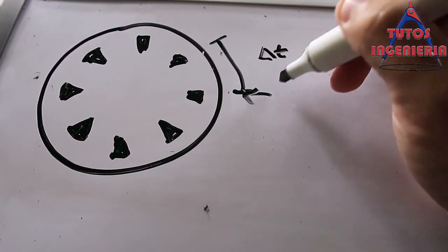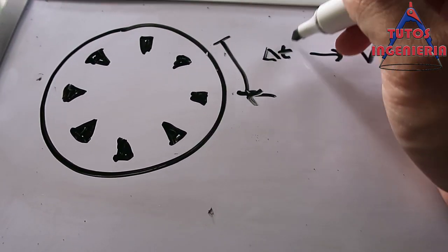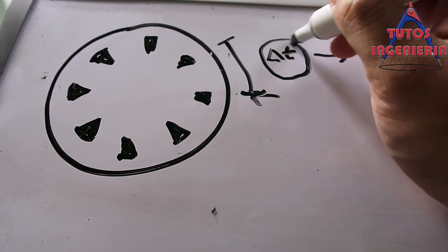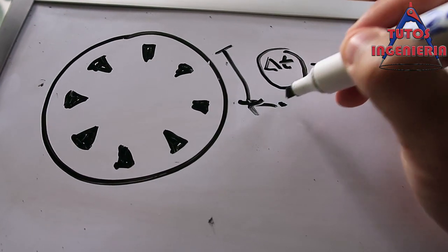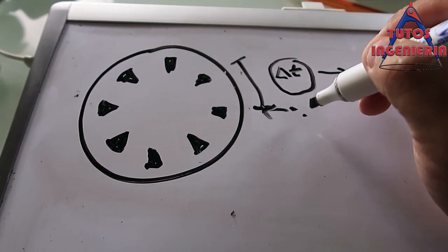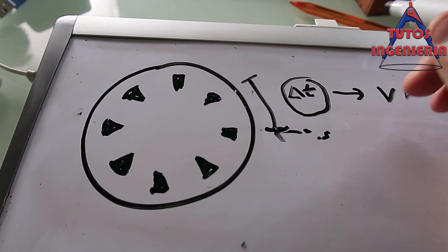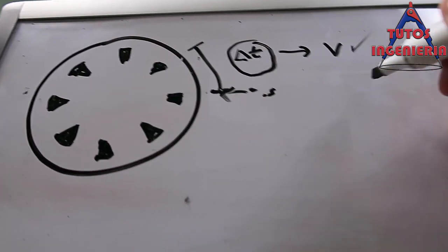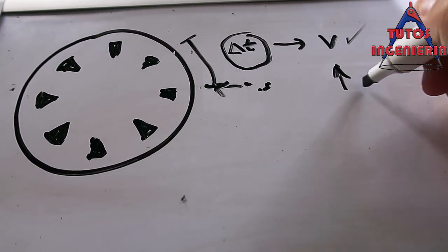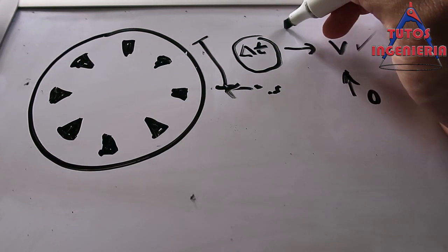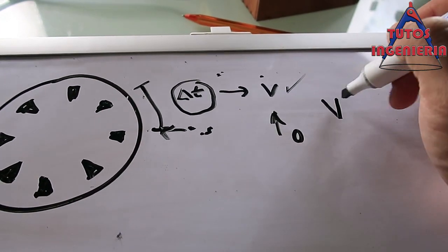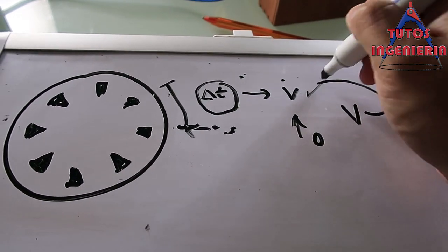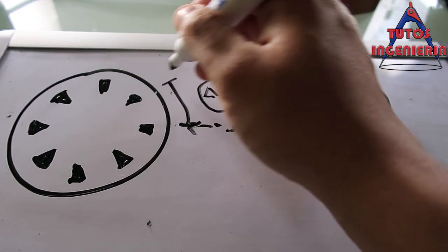If this interruption doesn't appear, that delta time can't be calculated. Then the velocity stays at the velocity from the last iteration. So the wheel has a velocity in the program, but in real life it is stopped, and that is a big problem.